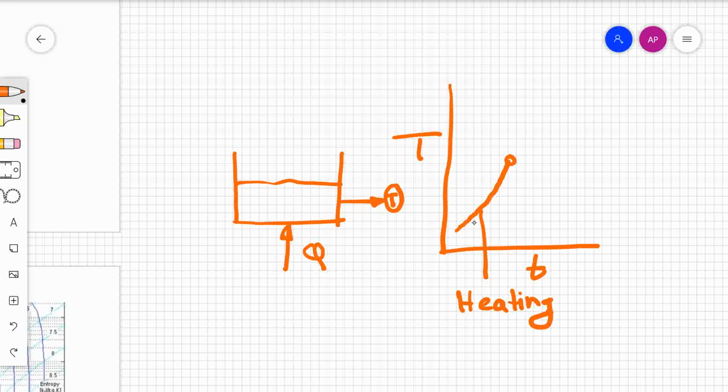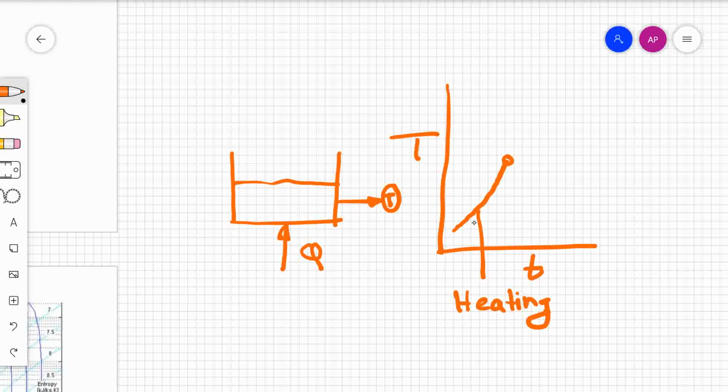Now, when it comes to the saturated temperature or the boiling temperature, whatever heat you give to it no longer is used to increase the temperature but is used to vaporize the fluid. So the temperature remains constant during boiling. Once again, when everything has been vaporized off and you further heat it up, the vapors are superheated.